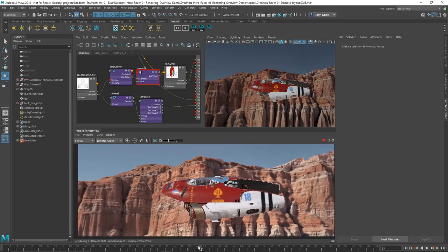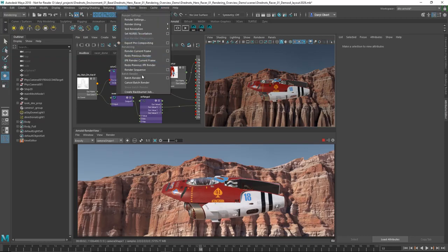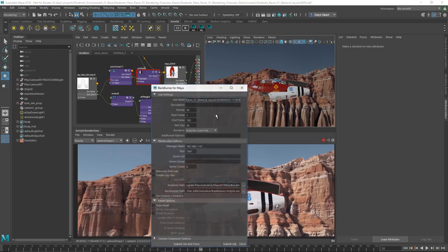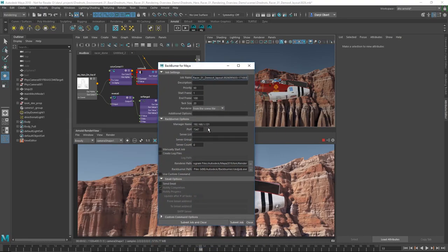The next thing that we want to do is launch this off as a batch process to render using that Arnold 5-pack. This is pretty cool. We're going to jump over to our rendering menu, go into the rendering setup, and I can basically start a background job using Backburner. What this is going to do is go through and find all the render nodes that I have on my local network.